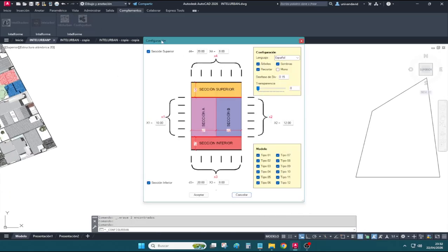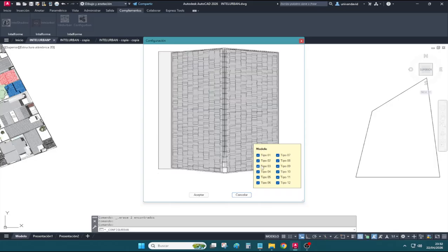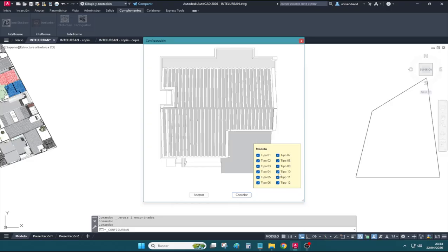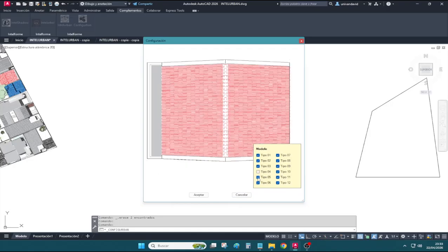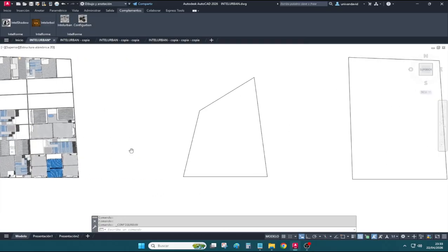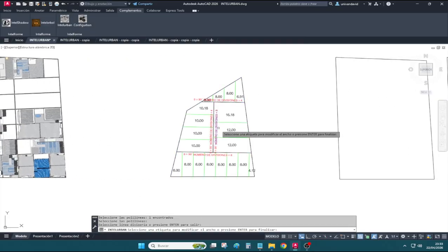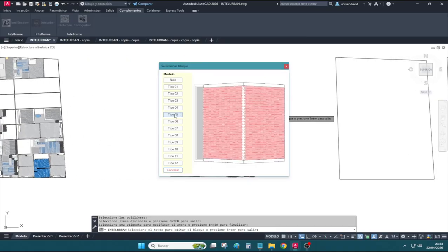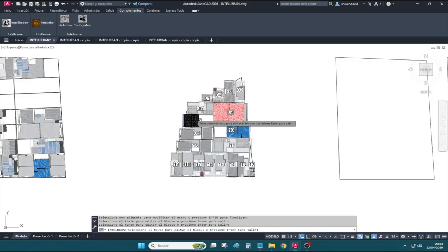Again, in Settings we can set which blocks the plugin uses by default to fill plots. Activate them in this list. Hover the cursor over list items to preview the highlighted block right in the panel each time. But even if we deactivate a block from the list, we can always choose them during the command's execution by clicking on the corresponding labels.